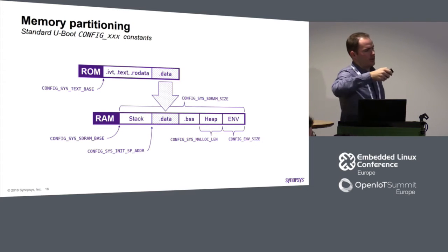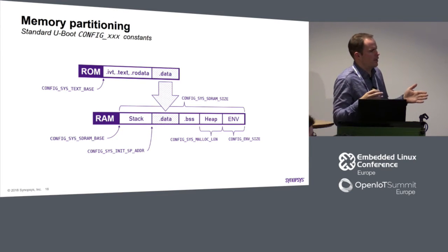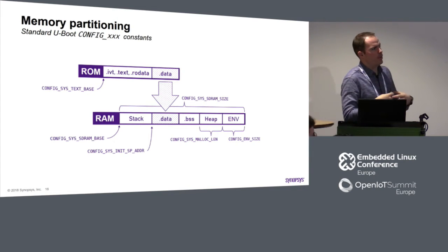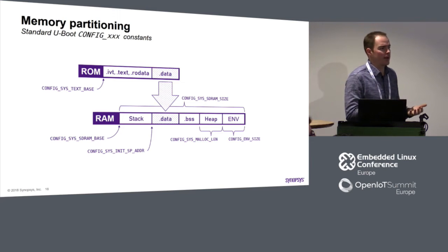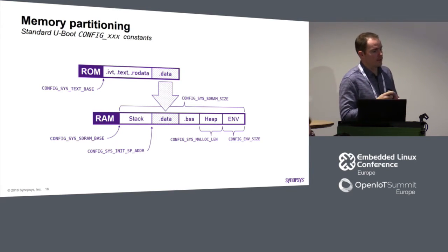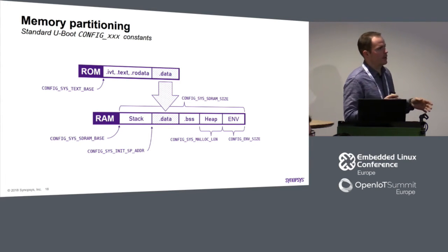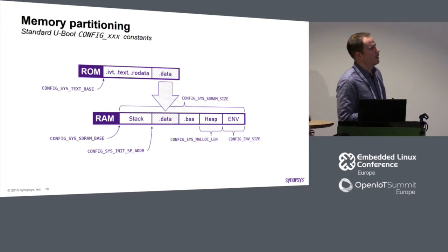First thing it does, it essentially allocates its space for itself if we are going to relocate. So somewhere here it would be place for the entire U-boot binary. And in fact, it was happening even if we signaled that we wanted to not relocate. So I had to change that and not relocate that again. For bigger platforms with more memory, we don't care, we allocate here 200 kilobytes, here 200 kilobytes, and don't care. But here I have to be very careful.